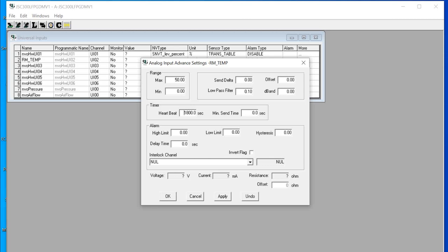So this one, you use the multimeter to verify. Another, you can use the AC voltage on the multimeter to measure whether there is any AC. Then if you really want to solve it, maybe use a hardware filter, like a capacitor and resistor filter. Like this, it is a software filter, right? If it is a real hardware issue, maybe you use the hardware filter.